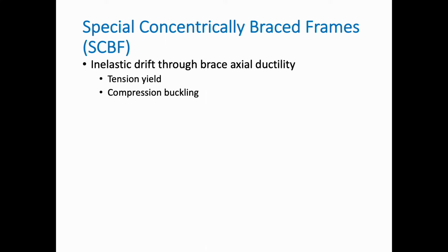So that is defined by the EI of the member, but that is followed by a local buckling, which is the plastic hinge formation in the member. So the mode of failure is quite different.